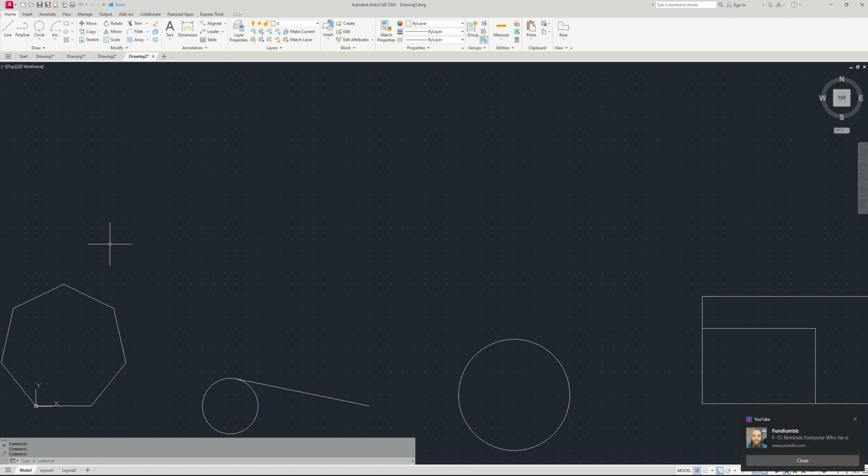Now, oftentimes our drawings are such that to simplify the complication or to bring more life to the drawing, we'll need to apply layers. I'm going to show you in this video how to make the layer settings and also apply them to your drawings. Okay, so first of all, with your mouse pointer, try and find the layer properties in the layer group.